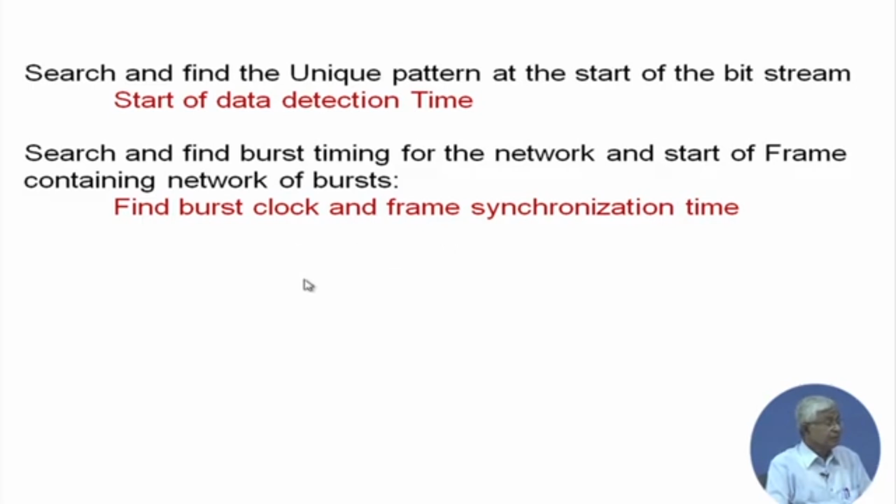You should know where the frame at the transponder has started, because a receiver will receive data bursts continuously, one after another. Which data burst is from whom, there has to be identification. So they identify it in terms of frame. Timing is given in each frame, and some time is given to each station to find out the frame timing.